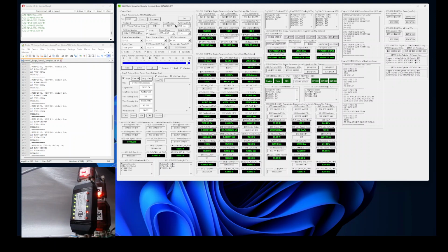After the serial number you can see the CAN baud rate. We support two different CAN baud rates, 250K and 500K. When you click 500K, it will automatically switch to 500K, and then you can click 250K, and it will switch back to 250K. And then this is the firmware build version or build number, so you know what firmware you have in the device itself.